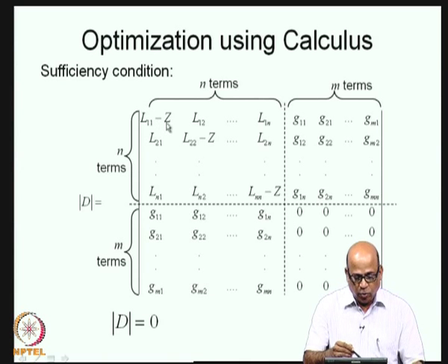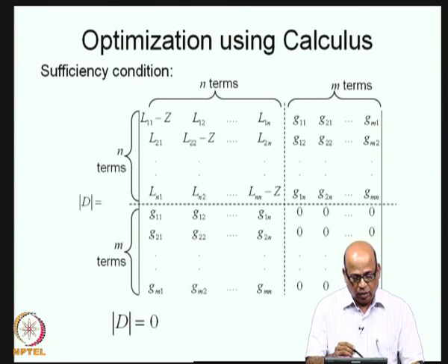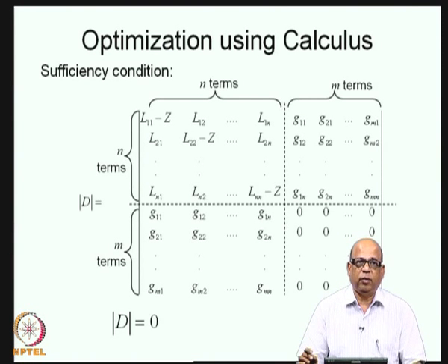When we do that, you get a polynomial in z. Remember, only z is unknown here, all other derivatives here are known and these are of course zeros. So, we get a polynomial of the order n minus m in z. We solve this for z and look at all the roots that we get for z.